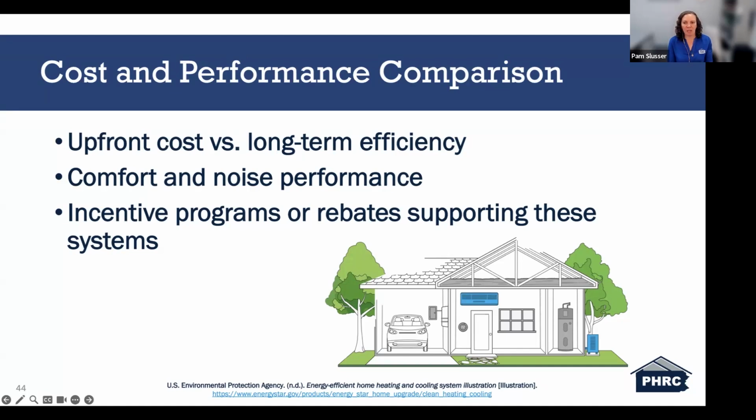There might be a little bit more that you have to do due to the design coordination or the soffits or drop ceilings, but at the end of the day, it can significantly reduce those losses. This helps systems perform closer to their intended efficiency, and it makes it easier to meet those code requirements regarding which compliance path that you're following as well, especially under the performance or the ERI methods.